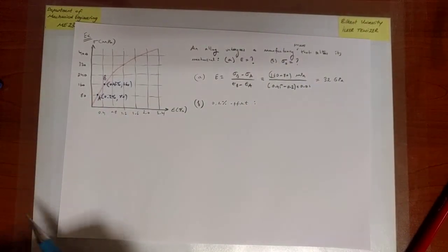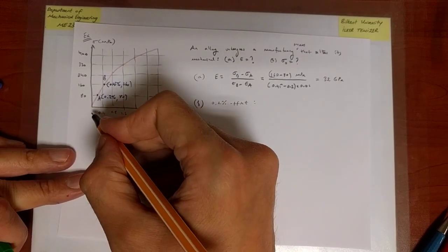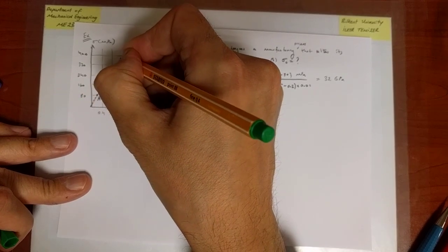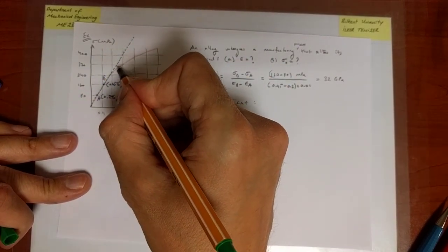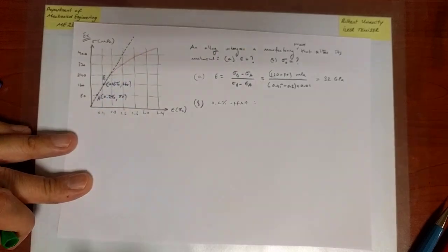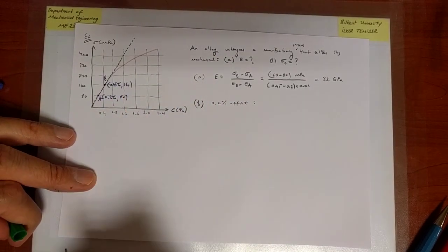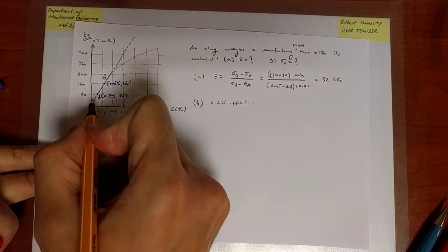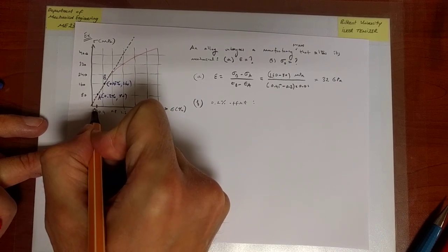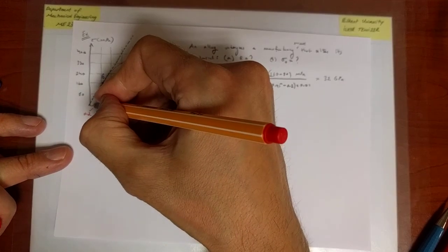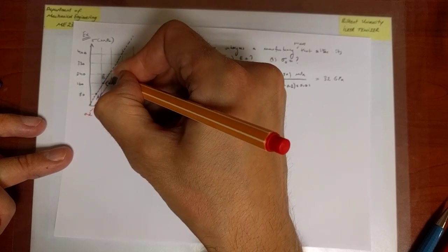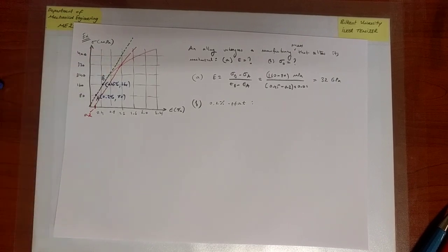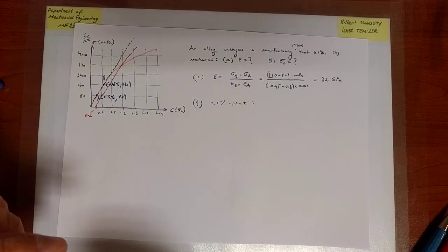So for the 0.2% offset, what I have to do is, first of all, my elastic loading line is this, and of course I don't proceed along that line. At some point there is a significant amount of plasticity occurring, so the red line is the actual data. Then I would draw a line offset by exactly 0.2% with the same slope, such that it intersects the red curve. And the point of intersection would be the yield strength.